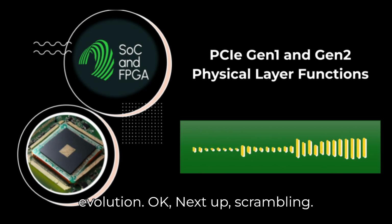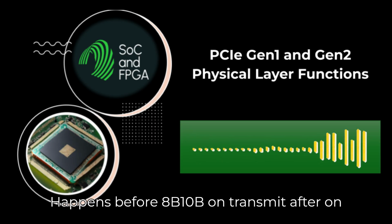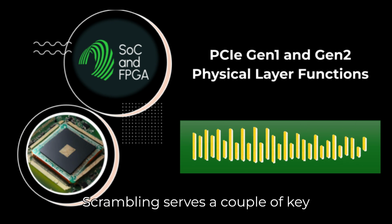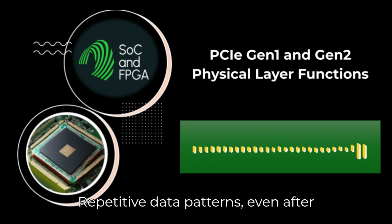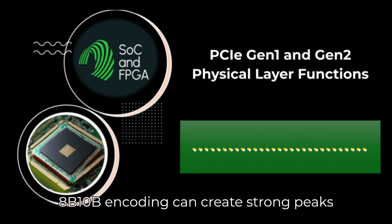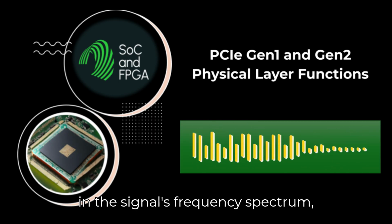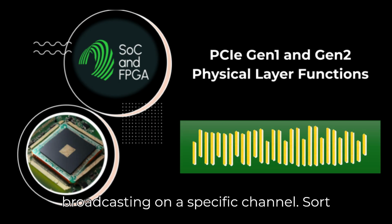Interesting evolution. Okay, next up, scrambling. Happens before 8B10B on transmit, after on receive. Why scramble if 8B10B already helps with transitions and balance? Scrambling serves a couple of key purposes. The big one is reducing EMI. Repetitive data patterns, even after 8B10B encoding, can create strong peaks in the signal's frequency spectrum, leading to unwanted radio emissions. Like broadcasting on a specific channel.